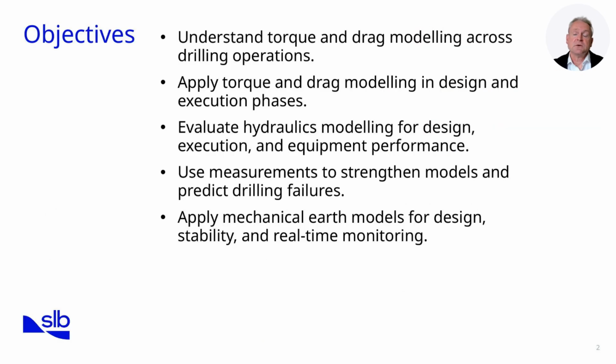In this sub-module, our goal is to strengthen your understanding of the modeling tools used in both the design and execution phases of drilling operations. First, we will look at torque and drag modeling and understand how it applies to different drilling activities such as rotating, sliding, and tripping operations. Next, we will apply this modeling in both design and execution to assess limitations and monitor performance.